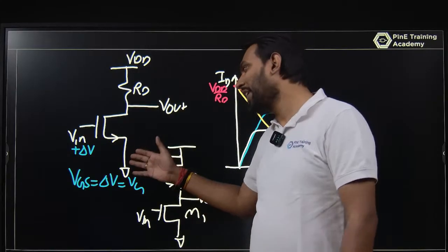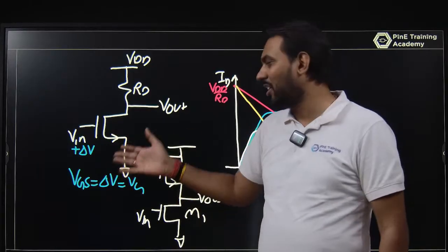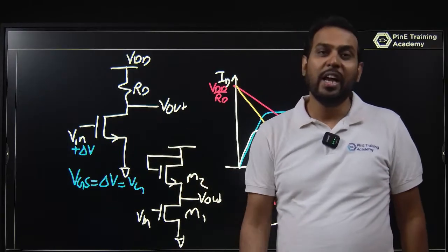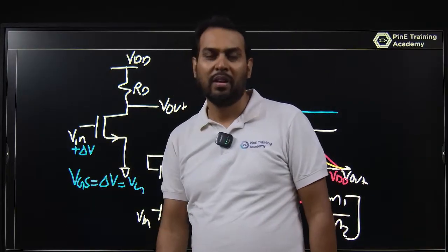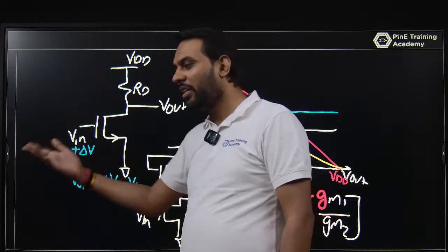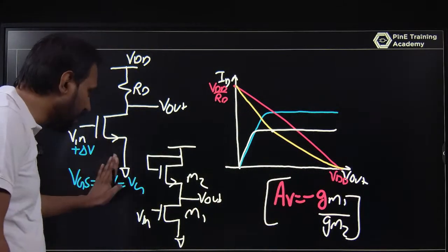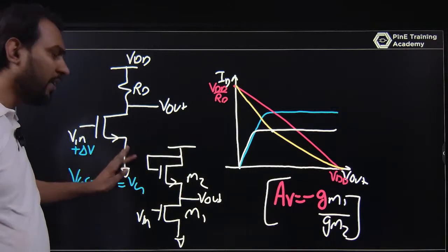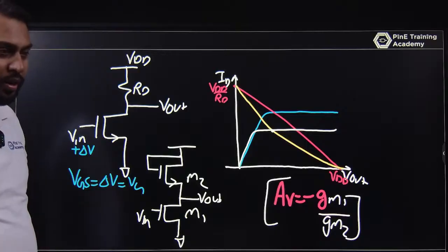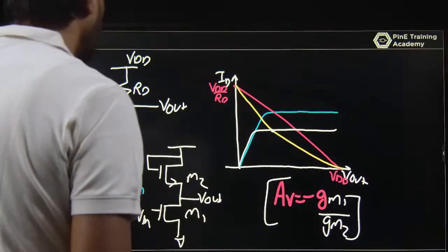If you use one resistance, the source resistance, it will protect your device. I think we will discuss source degeneration in the next class. But now the source is simply grounded; I am not using any resistance here. Yes, is it okay? Sure. Great.